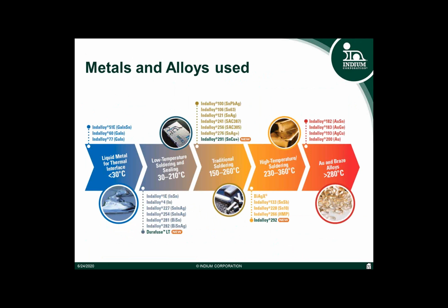And we're here at Indium Corporation. We are manufacturing alloys from the liquid stage. So we're using alloys that remain liquid at room temperature, right the way through to the gold containing and some braze alloys that are in excess of 280 degrees Celsius. So if there is a potential need for a step solder, I'm sure there's an option of an alloy in the market out there.